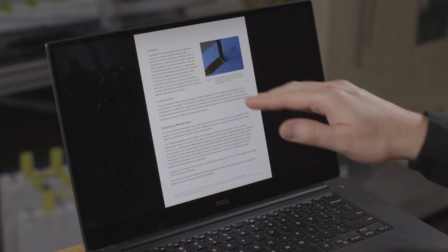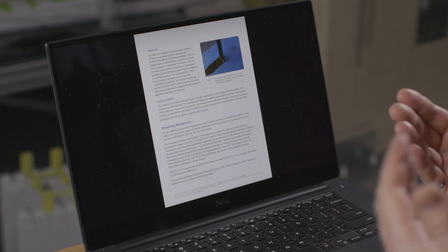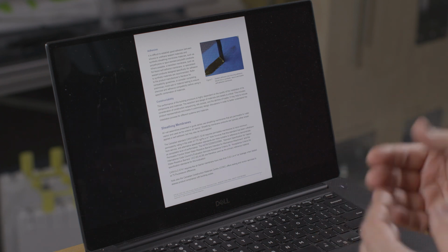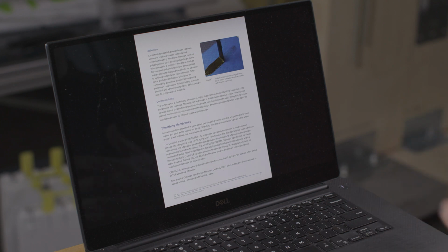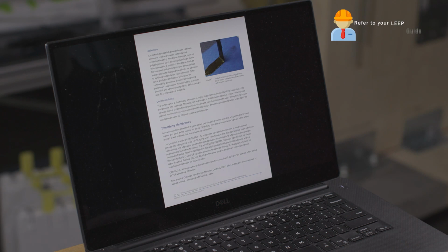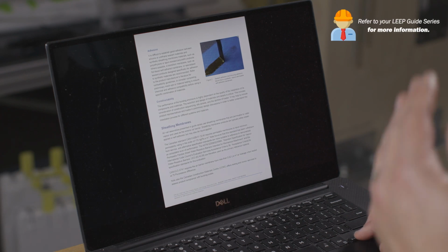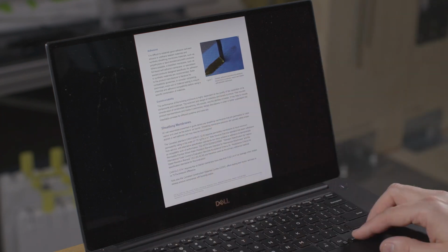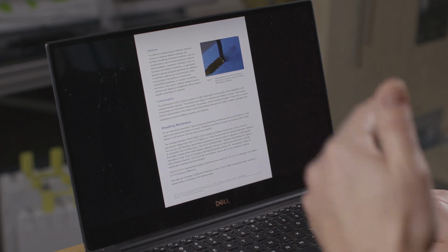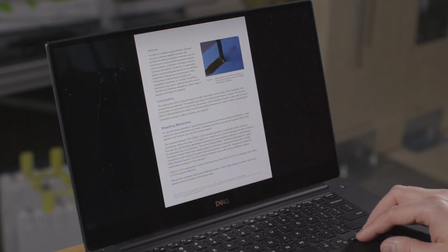Okay. Constructability. Of course, if you're using tapes and sealants and sequencing, applying in cold weather, in rain, and to damp materials, all these things come into play. So the first thing we're going to look at is sheathing membranes. So sheathing membranes have a number of code requirements that are covered here, both be used as an air and a water resistant barrier. So if you're using that sheathing membrane as the air barrier and the water resistant barrier, it needs to be tested and evaluated as such.